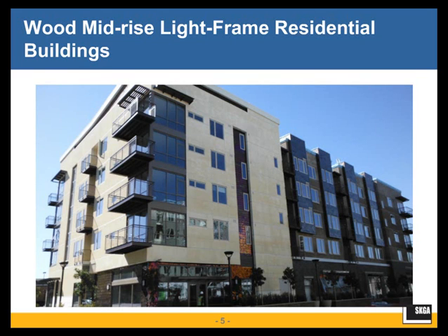So when the structural design of a wood multi-unit light frame residential building commences, there are many decisions that have to be made which will affect the design. What type of framing are we using? Joists or I-joists or sawn lumber? What direction will the framing be running? Can we get mechanical ducts into the joist bays? In which direction are the units to be vented, horizontally or vertically?